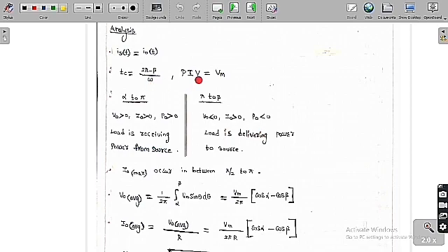And the peak inverse voltage of the thyristor is equal to Vm. Just now I have told you. So from alpha to pi, I have already told you that V0 is greater than 0 and also I0 is greater than 0. So therefore power is greater than 0. So from alpha to pi, the output voltage is greater than 0 and the output current is also greater than 0. So if we take the product of these two things, then the power is also greater than 0.